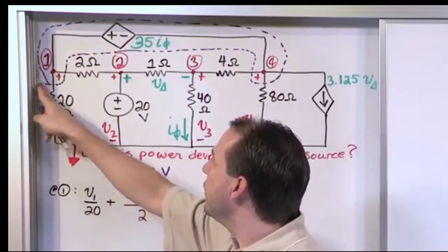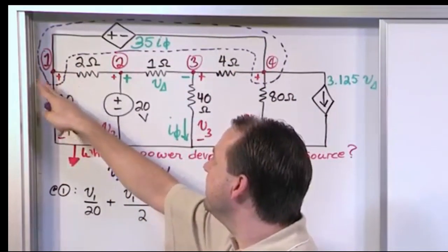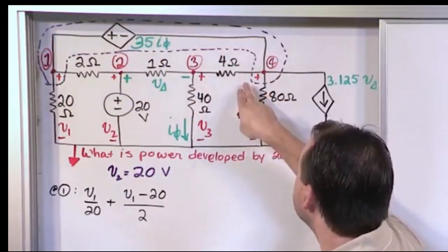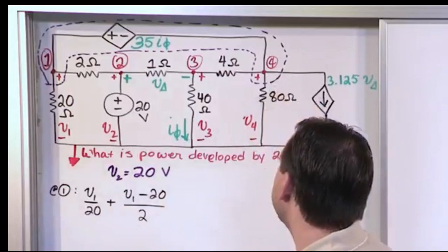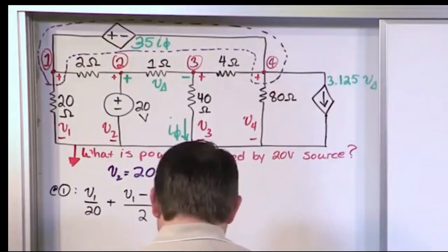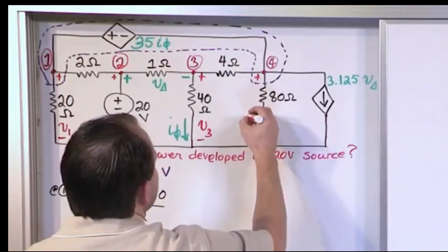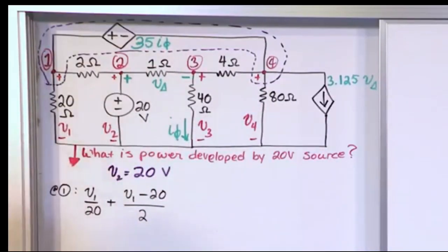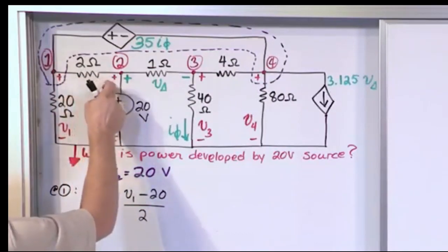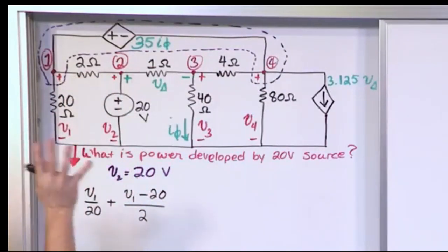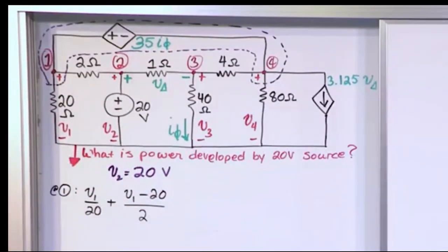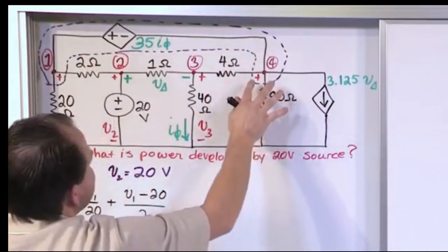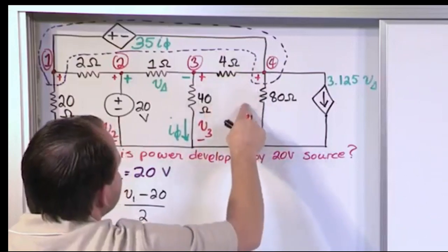The current flowing through these legs into this blobby region and going all through this stuff has got to be equal to the current coming out the other side. So right out of the gate, we have kind of a complicated equation. We have current going through here, current going through here. Okay, now this is a supernode. We're going to pretend that this is physically the same node as over here. So the other part of this node is this leg, and this leg.